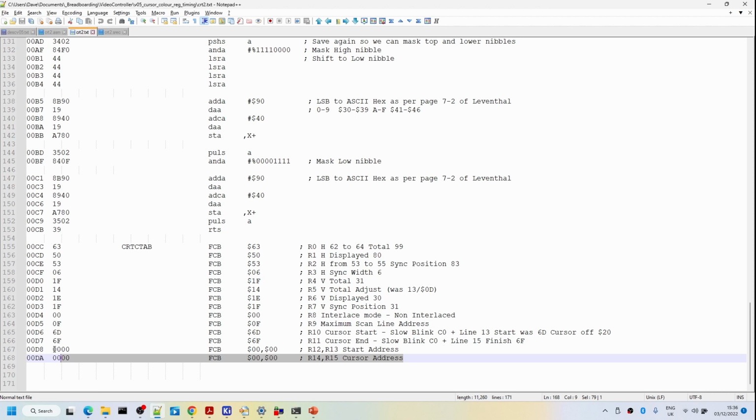So the easiest way to do that is I'm just going on to the Nanocomp keypad here for 00 DB. All I'm going to do now is to put in 09 there, so I'd expect that to be around about character 10 on the display. And what I'm also going to do is to just go into the values for D6 here, 00 D6, and I'm going to change this to 60. So this should make the cursor a solid block. So all I need to do is just to execute that, and that should have updated the settings.